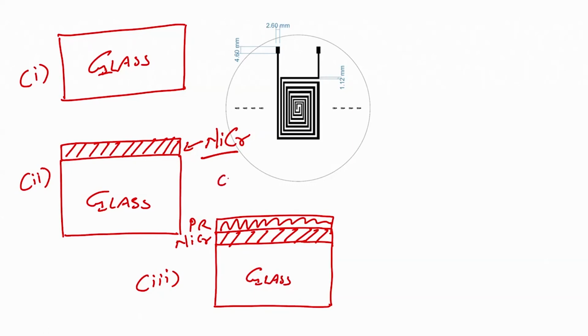The next step, which is my fourth step, would be to load the mask, right. I have to load the mask so that I can perform photolithography, correct. So, I am loading a bright field mask. What kind of mask am I loading? Bright field mask. Now, what kind of photoresist do I have? Positive photoresist.